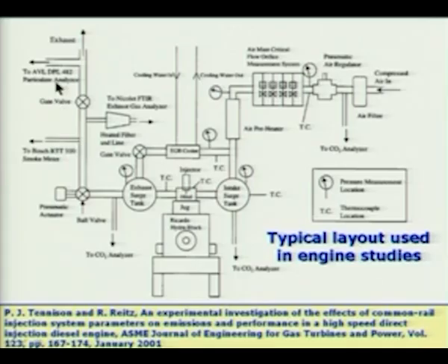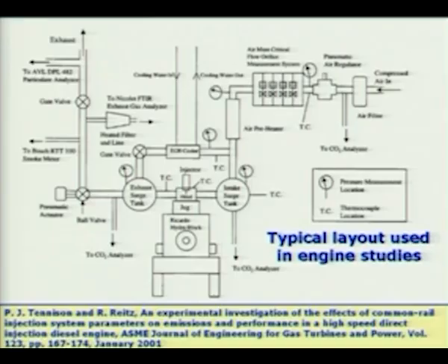You also have a particle analyzer to find out the diameter of the particles, the size distribution, and the number, and so on. Of course, we have not covered a discussion of particle size measuring devices. They usually operate on the principle of the scattering of radiation from the particles, and by looking at the scatter pattern of the particles, one can in fact get an idea as to the diameter and the distribution and so on. So, this is the particulate analyzer.